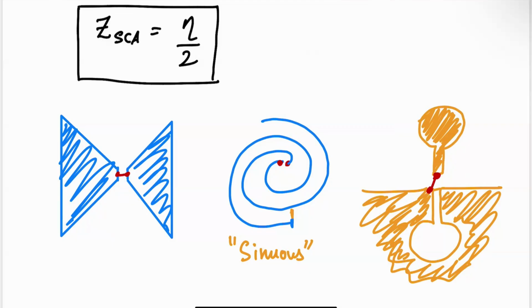One more thing I want to mention is that Babinet only guarantees broad bandwidth in terms of impedance bandwidth, right? The impedance is broad over the entire band. Not all self-complementary structures are equally good. Like for example, this top-loaded dipole on the right side, this is not really very symmetric in some sense, right? So over different parts of the bandwidth, the radiation pattern can change quite a bit.